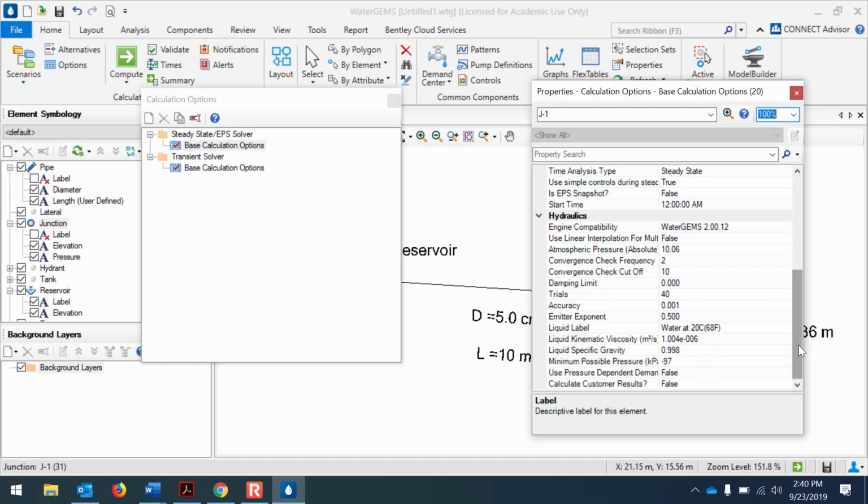Okay, so water at 20 degrees Celsius, I think that it says the specific gravity is 0.998. So it's not 9810 newtons per cubic meter. The unit weight it's using in the calculations is 0.998 times 9810 newtons per meter cubed. So what is that if you've got the calculator? 0.998 times 9810. 9790.4. Okay, so 9790.4 newtons per cubic meter.